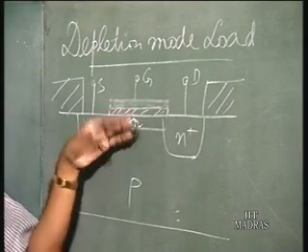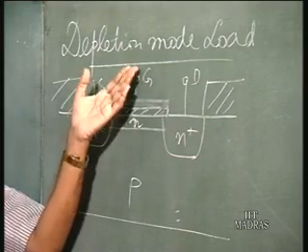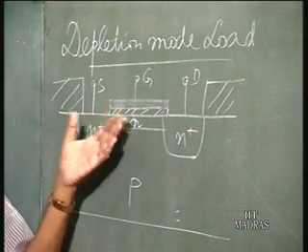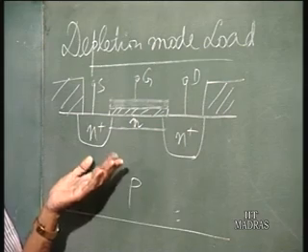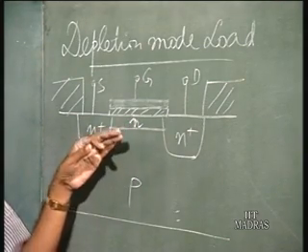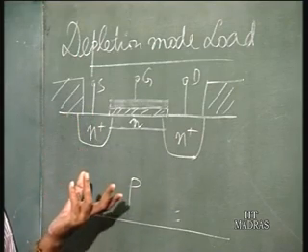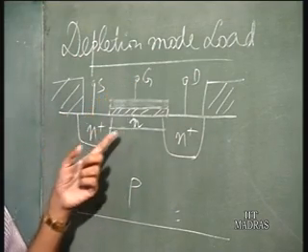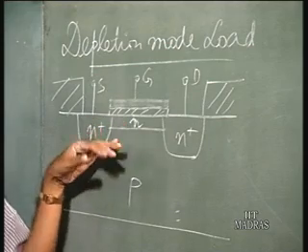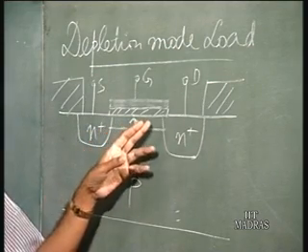you have a larger concentration of electrons. If you have positive here, you introduce more electrons, and the current goes on increasing, just like in the case of an enhancement type device. But when you apply a negative gate voltage, you should induce positive charges in the semiconductor.